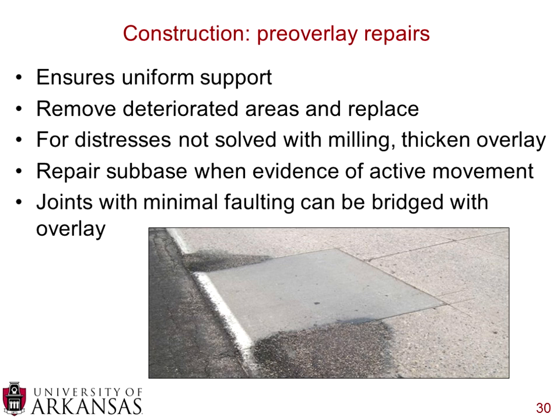It's very important to repair the subbase when there's evidence of active movement. So we talked a little bit about pumping in a previous slide. If you do see pumping, material coming up into the pavement layer, then you want to make sure to address that issue before moving on, because if you're building on a weak support, it really doesn't matter what you're going to put on top of that, you're going to have problems down the road.